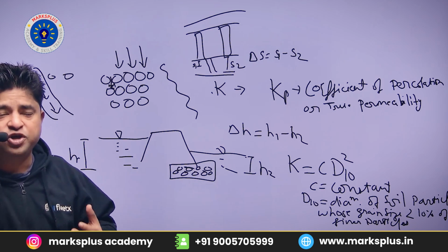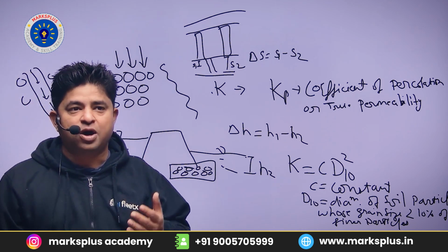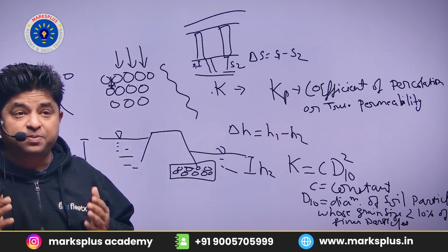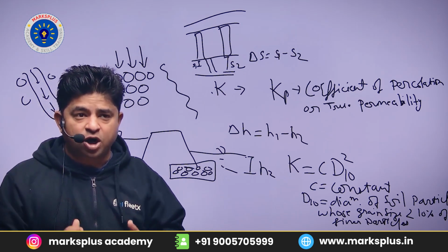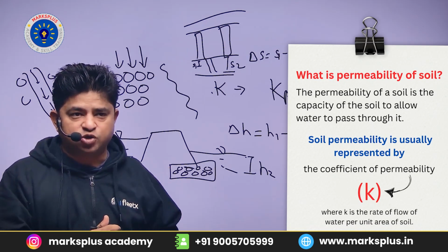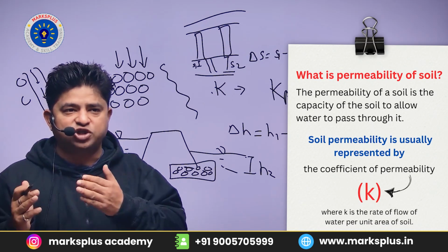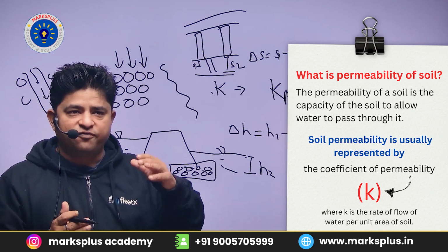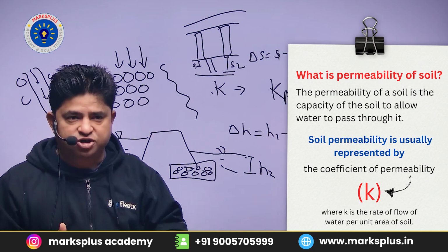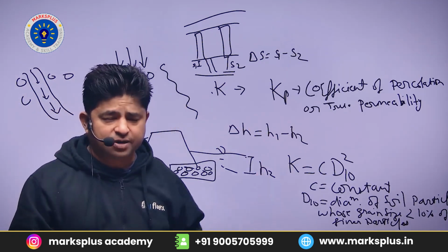For that it is required that we understand the permeability. So as you have seen, permeability plays a very important role before designing any structure, because it is a property of the soil that allows the flow of fluid through it. If our flow is high, it may cause settlement of that particular construction, and it may result in failure of that particular structure.